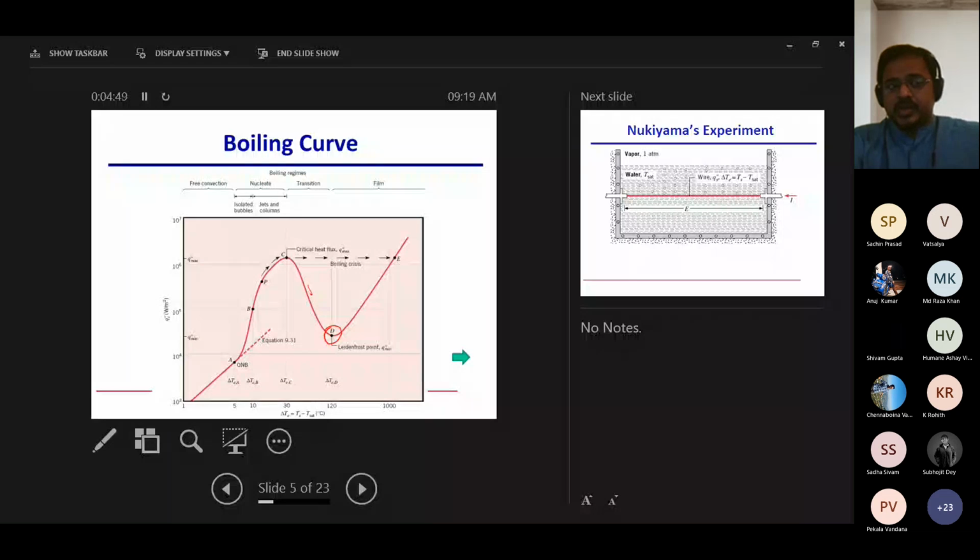This is the Leidenfrost point. Because what happens is he reaches a point where part of the liquid boils off, but forms this layer of vapor on the surface. And then the remaining liquid, in these droplets, is dancing on that vapor film. So that is this Leidenfrost point. When this phenomenon happens, it may not exactly be Leidenfrost, but somewhere around, the person who is cooking decides that this has heated up enough, and so now I can cook.